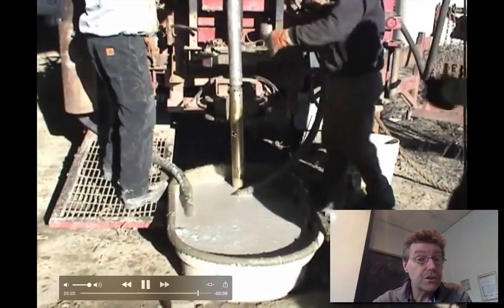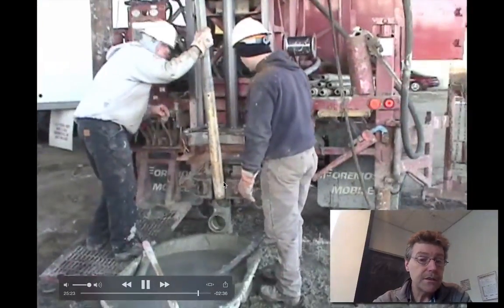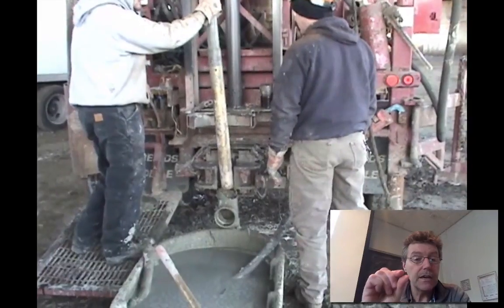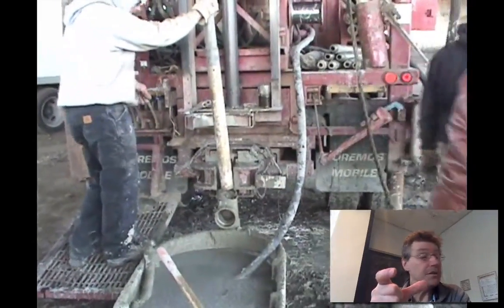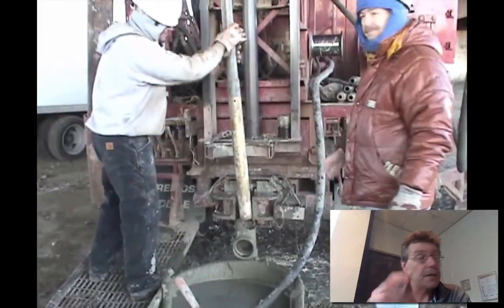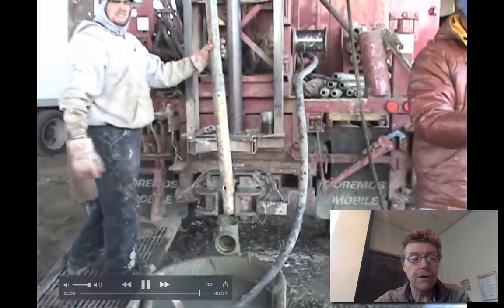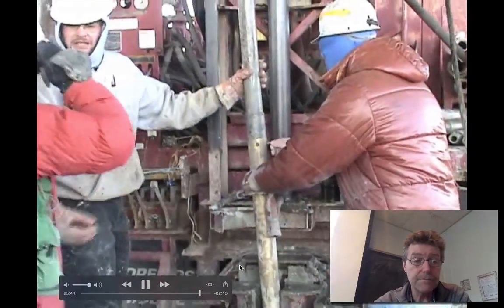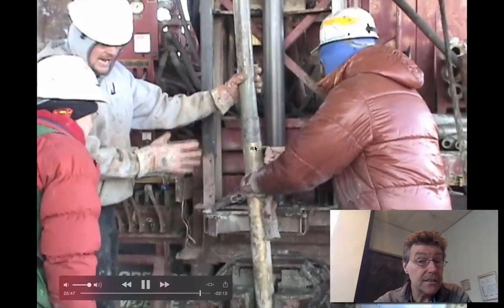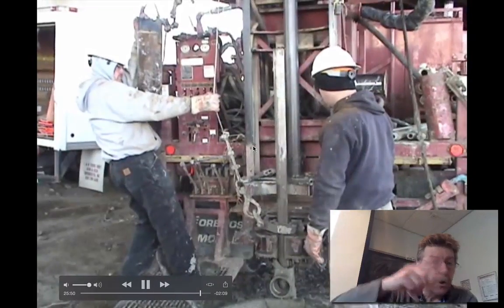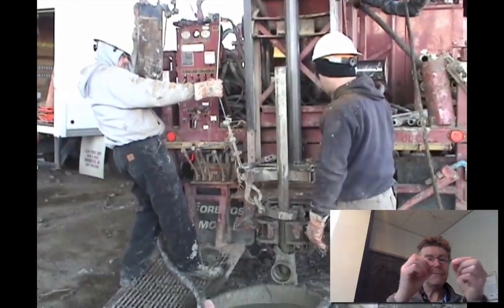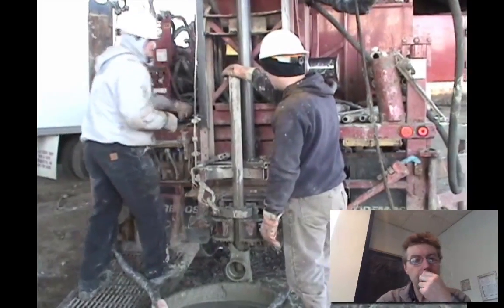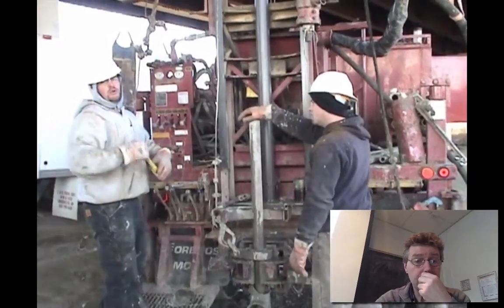This is called a thin wall sampler, or a Shelby tube. It's a tube that might be an 1/8 or a 1/16 of an inch in wall thickness, maybe 2 inches in diameter, sharp enough on its tip to cut you if you get your finger in the wrong place. It's just getting ready to be dropped down inside the sampling hole at this time. It's locked on with Allen keys. The Allen keys go into the sampler and leave wide collared holes, so you don't actually take the Allen keys out. You screw them in, and then the sampler falls off after you've done your sampling.